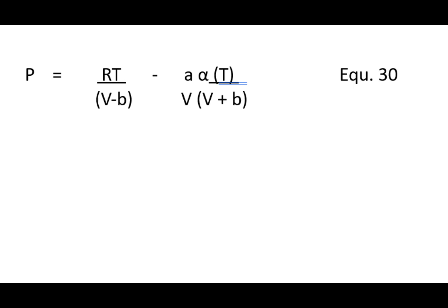The SRK equation of state is an equation that models real gas behavior by accounting for intermolecular forces and the volume occupied by gas molecules. It is especially useful in the chemical engineering and petroleum industry for predicting phase behavior and compressibility factors in gases and liquids, where P equals pressure of the gas, R equals universal gas constant, T equals temperature, V equals molar volume of the gas, volume per mole.